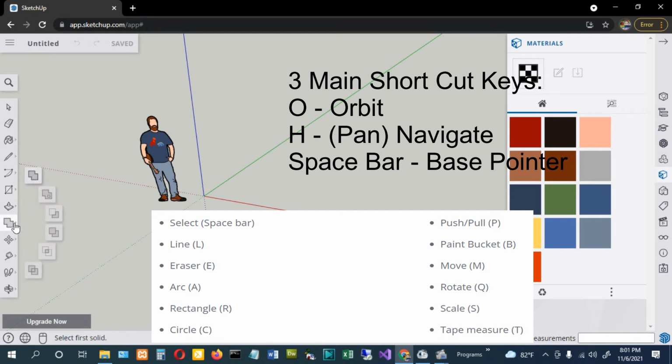So the next is this one. We have a lot of options here. So the first one is the outer shell. So this is about grouping, right? Tools union, this one, to group the object, 3D or 2D, and then tools to subtract, this one, if you want to remove some part of the object, right? This one is to trim, to cut the object, and this one is tools intersect, right? And this one is tools split, to split the object, right?